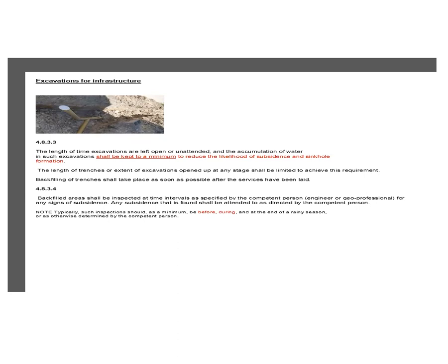So guys, it shall be kept to a minimum to reduce the likelihood of subsidence and sinkholes. The trenches mustn't be long lengths. They should be kept short and shall be limited so that they're not open for long times. Regarding backfilling of the trenches, it should take place as soon as possible. And obviously, the other thing on that is that backfilling needs to be done in accordance with specific requirements from a competent person, engineer. They may say, listen, we want you to fill it like this and like that and with that substrate.